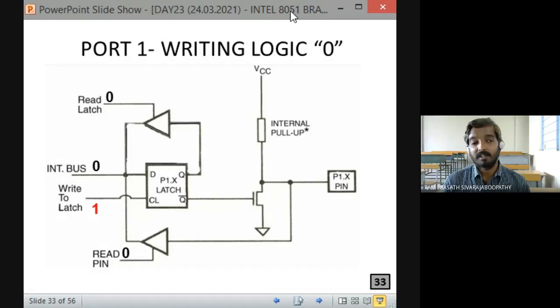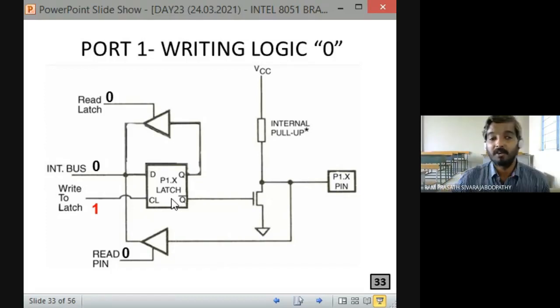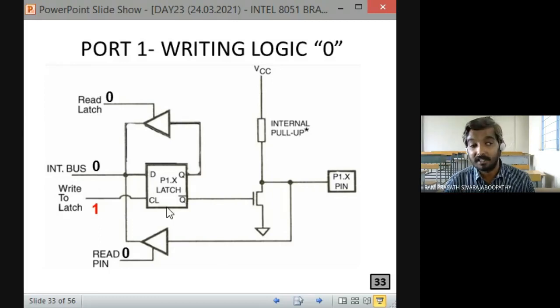How is it 1? See, 1, it is an enable signal here. That's why it is mentioned as latch. When we say flip-flop, what have we studied? We have studied the clock input. So here also we are having a clock only. When this pin is getting 1, whatever data we are having at D, it is getting into the latch. Correct? So what will get stored inside?